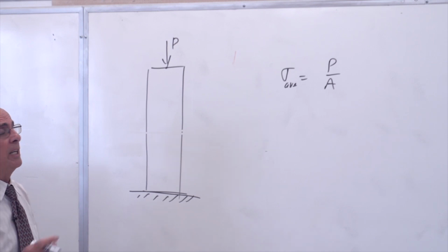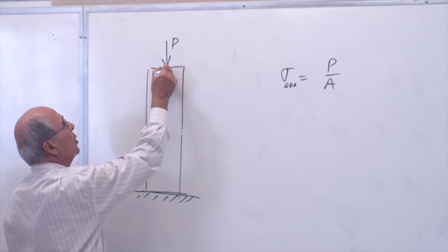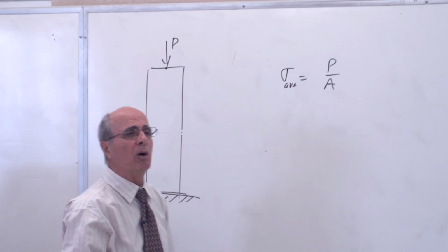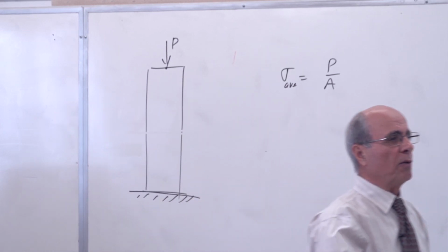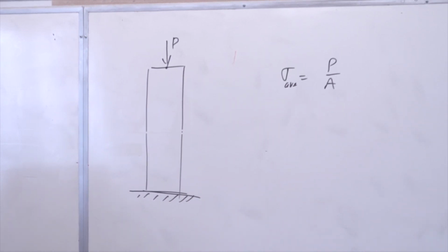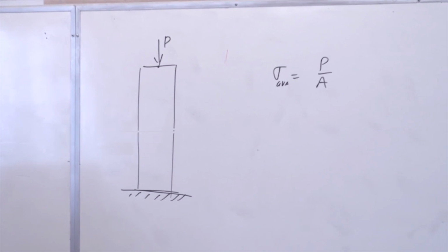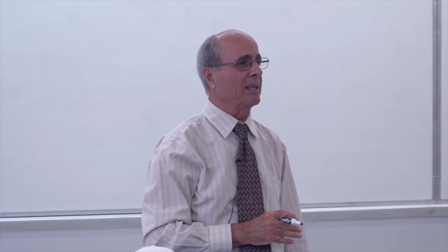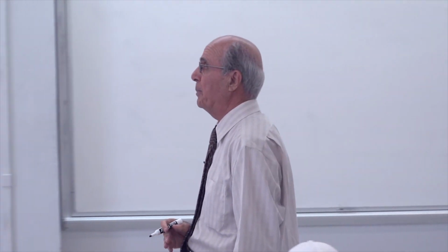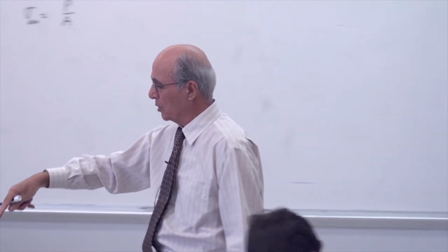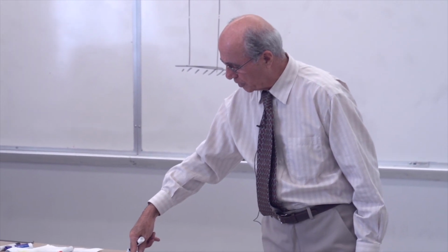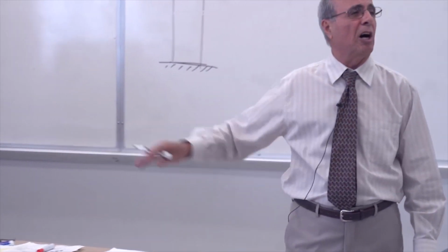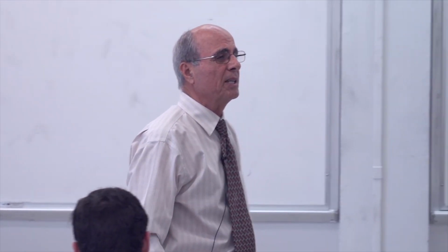In actuality, if I put this P here at this point has an area equal to 0, yes or no? So force over 0 should be infinity. So under the load, I should get huge stress. Everybody understand that? And which is the fact. It will happen if I put my hand here. Look, if I put it here, look how stress is there, nothing around outside. Everybody understand what I'm saying there?